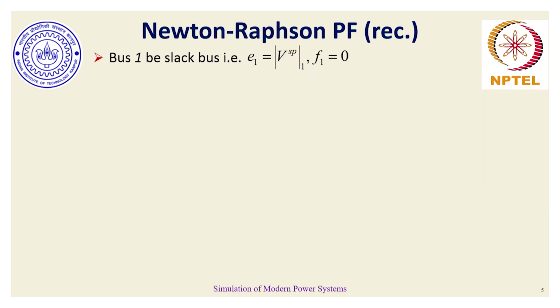So, to verify or confirm the details of how Newton-Raphson would look when voltage phasors are in rectangular coordinates, we will start with the same assumption, that is, for the sake of convenience, I would choose bus 1 to be a slack bus. Please note that when I define a slack bus, I would essentially need a generator to be connected to it. And with the discussion that we have had in the past, generally the bus to which the largest generator is connected can be considered to be a slack bus.